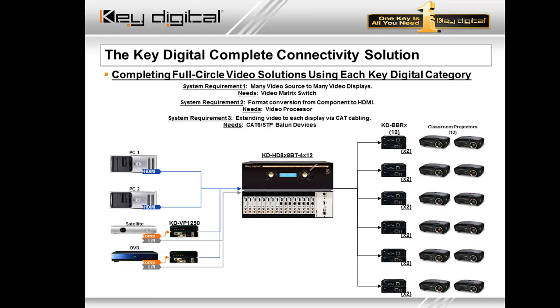This is the most common application for a VP1250, which is just every source that is outside of the majority rules format of the system gets its own VP1250. In this case, these two component video sources are converted to HDMI and scaled to the resolution that you set in the 1250, again, not via the EDID there.